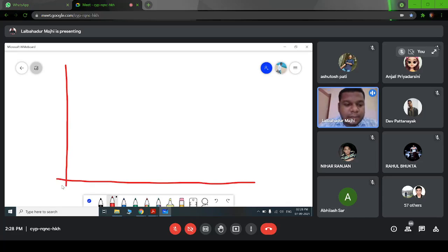So I am starting from frequency 1, then this is 10, this is 100, and this is 1000. We have corner frequencies up to 1000. First we have to find the initial point. It is a type 1 system, so we cannot take 20 log k.